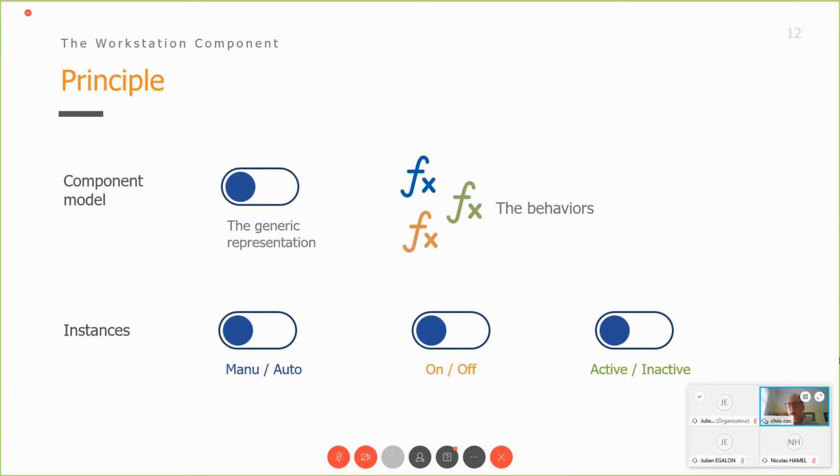And so the notion of the workstation object, the workstation component, is that when we cut and paste it, it will produce an instance. So it will produce a unique set of data for that button. And whilst a simple type of button like this may not benefit greatly, when you make these buttons more and more complex, so for example, if we add some interaction, that when we interact with the mouse with this button, we end up with a highlight to show the operator that he's actually got this button currently active, that would use a piece of local data in the button, which you would have to reconfigure if you just cut and pasted it. But effectively, when you have a component, you set it once in the component, and that's it. It works everywhere, and it's unique for every button.